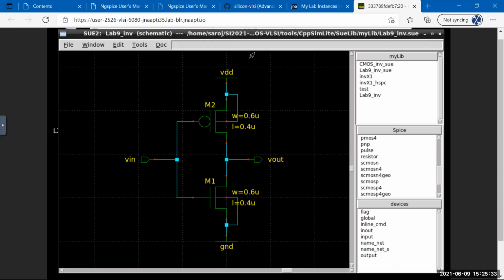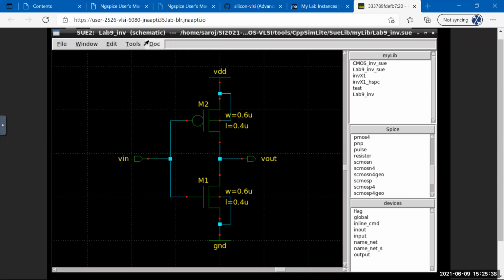So Ashwini, while you're catching up, I'll just start showing this. So now what we need to do is we are going to create a netlist out of this, right? You wrote everything by hand before, right? Now we are going to generate it automatically from this window, so you don't have to do connections by hand, which is good because with complicated circuits you just can't do it by hand; invariably you're going to make mistakes.